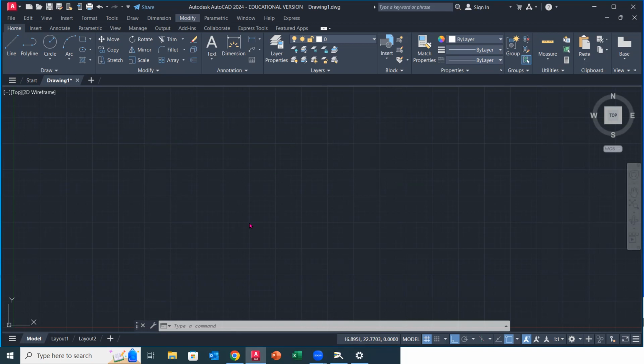All right. Now, whenever we're kind of done with AutoCAD, we need to leave and get out. So before we leave and get out though, the way that the startup menu started for us is kind of a generic way of doing it. There's a better one. So before we leave here, we're going to go down to our command line. Now our command line, we can type in there. So if you put your cursor down in there and you left click, we can start typing now. And what we're going to type is startup, all one word, startup. Okay. And you're just going to hit enter.